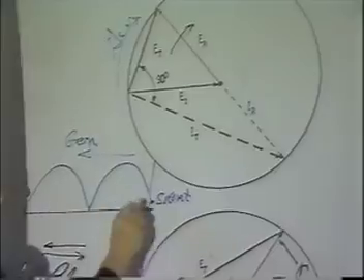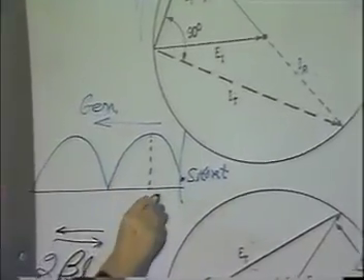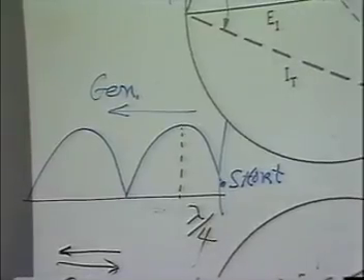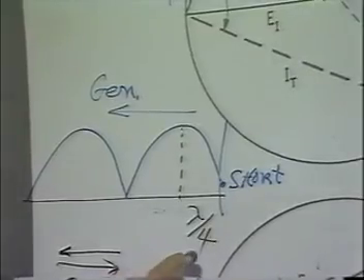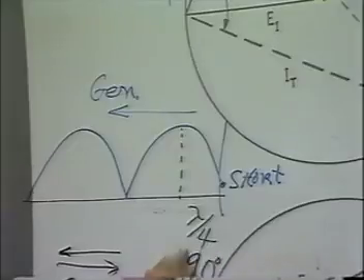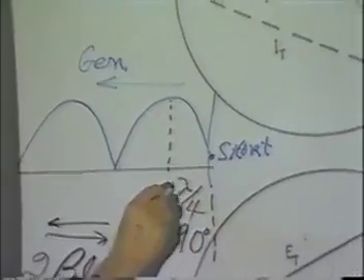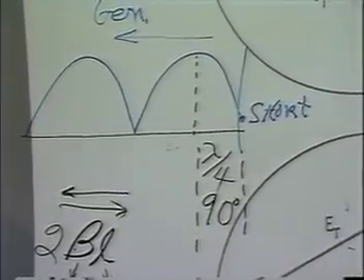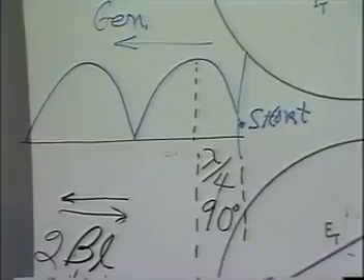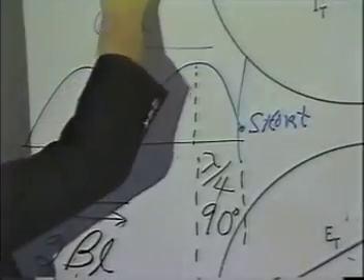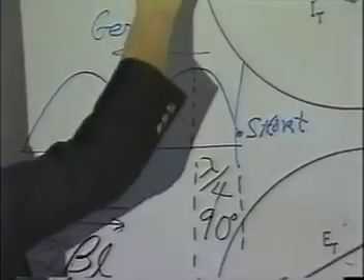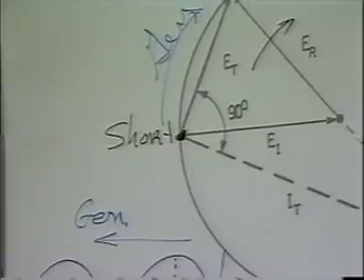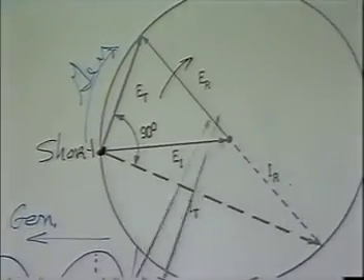Now notice the significance of that. If you look at this from the standpoint of this point here, this is how much of a wavelength? 1/4 of a wavelength. How many degrees is that? 90 degrees. That's from here to here. 90 degrees. Now, isn't it very simple on the chart? If this then is a short at this point, how do I know that's a short at that point? Here's E sub I to the right. If E sub R,